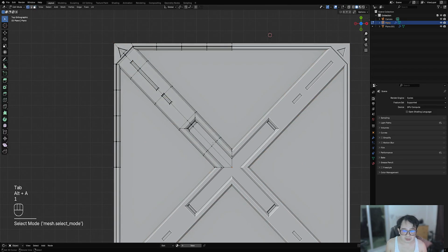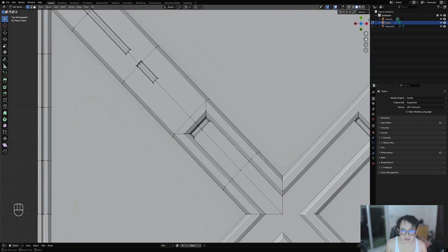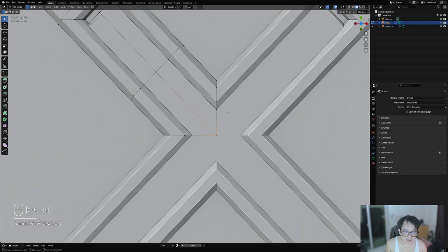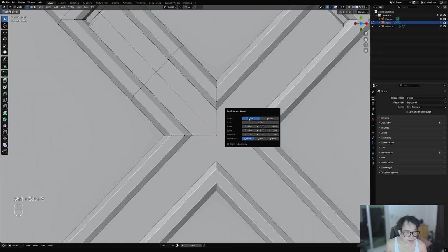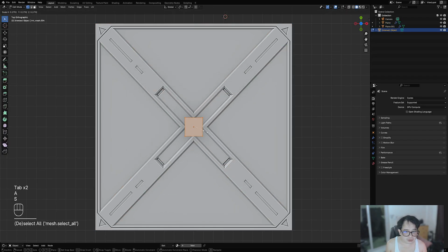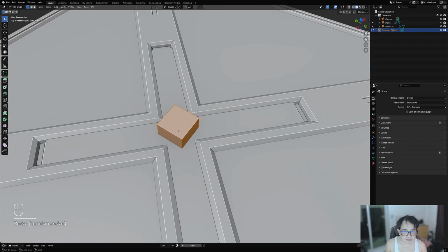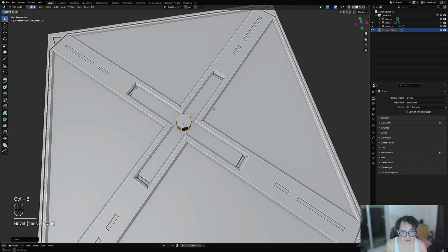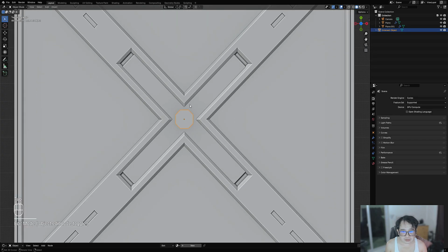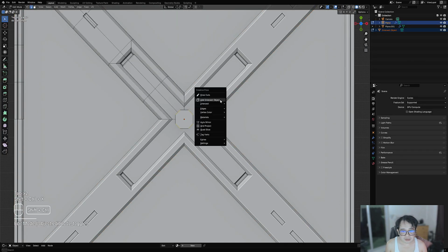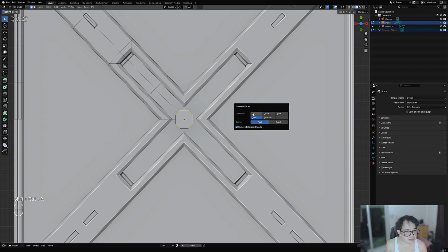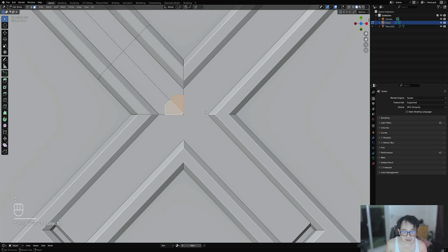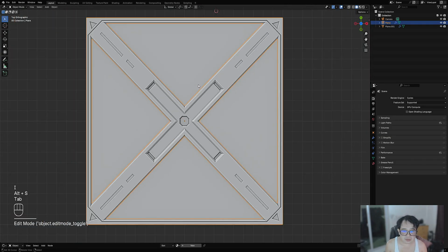so the intersect feature makes it easier to just position stuff, and then just draw the shape, edit the shape of the intersect object, and basically just draw the detail on your source mesh. Intersect and cut. Oops, not cut. Draw that.